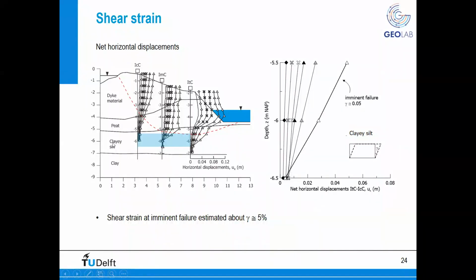And this is basically a cross section with all the different measurements in terms of inclinometer. So the failure was basically composed by a sub-horizontal movement started at the toe of the dike and then retrogressively propagating towards the crest of the dike. Here you see basically a very large displacement of the pit, which is extremely important.